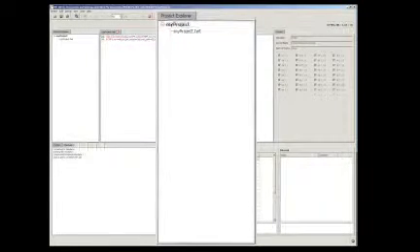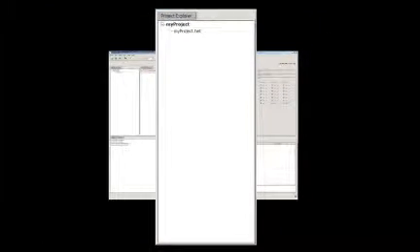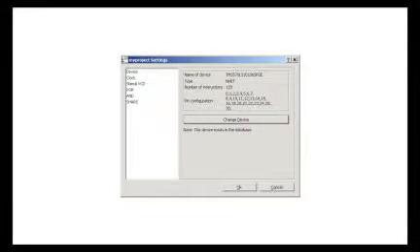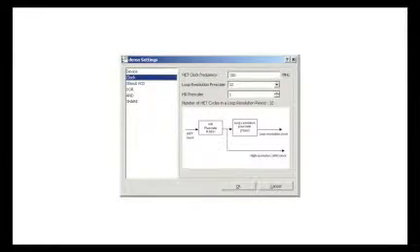The first thing to do to start developing and debugging HET code is to create a project. To do this, you will need to select the TMS 570 device that you are using, then your clock frequency, and finally the two ratios used for the generation of the high-resolution clock and the loop resolution clock. Please refer to the technical reference manual for more technical details regarding these clocks. By right-clicking on the project, you can select and save the setup properties. Once a project has been created, your HET code development can begin.